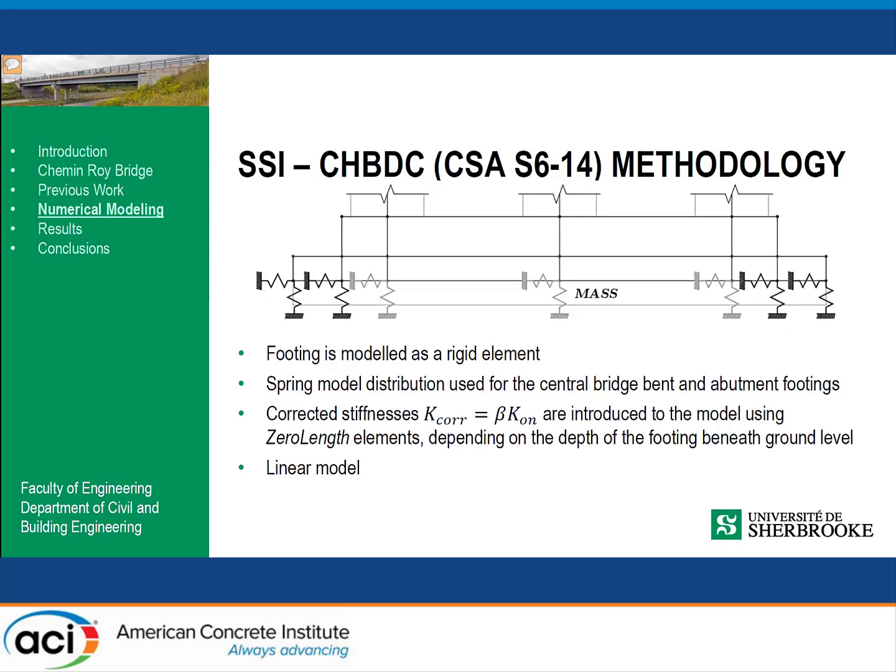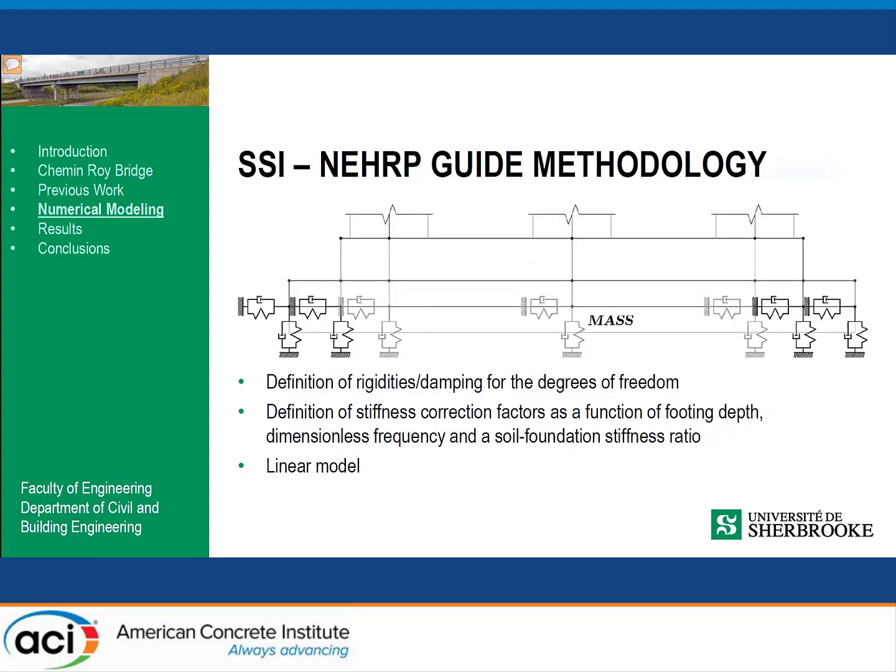The first one is the Canadian Highway Bridge Design Code, the S6-14 methodology, in which the footing is modeled as a rigid element. It's a spring model distribution, a really simple spring model distribution. It is linear. And also the NEHRP methodology, which considers also damping and is also a linear model. So really two simplified models.